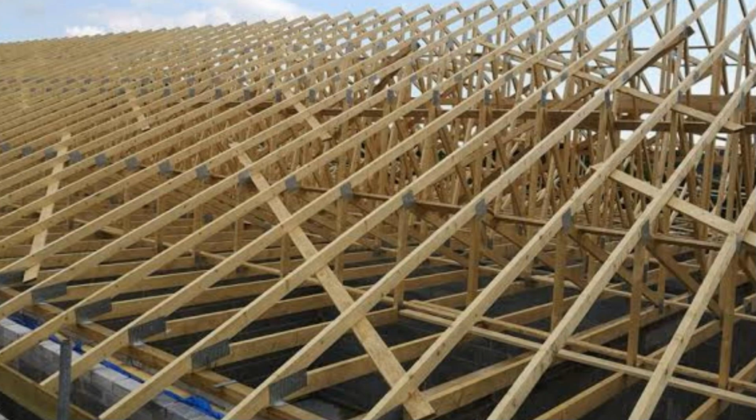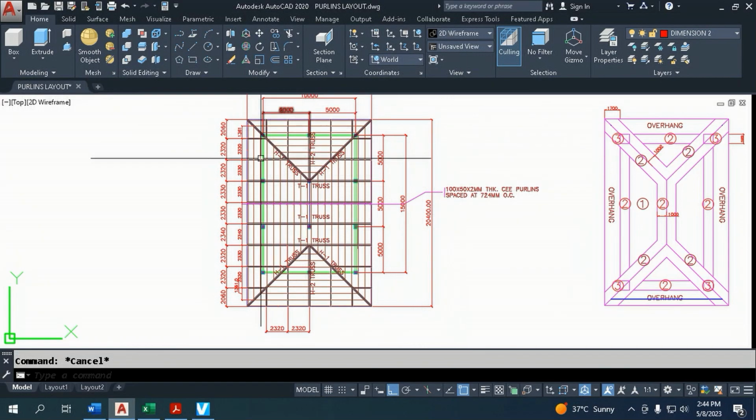To design purlins from our floor framing plan, these are the purlins in this roof framing that we would be designing. We will design purlins in the area where net wind pressure is higher. There is no need for us to design all these purlins here one by one. We chose 2 locations only.